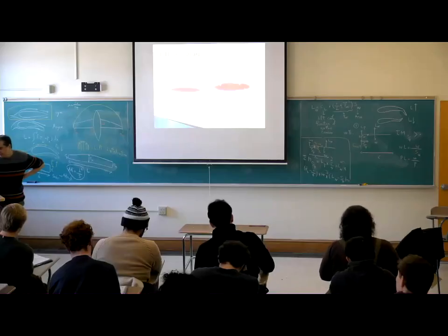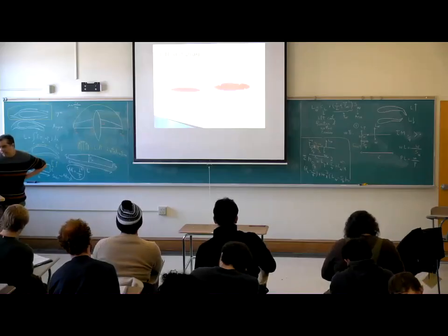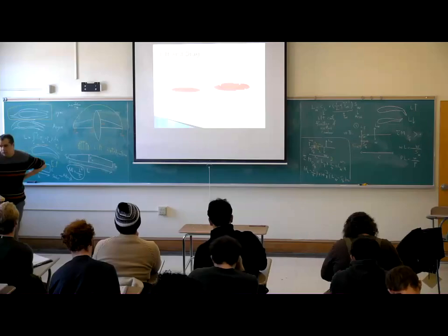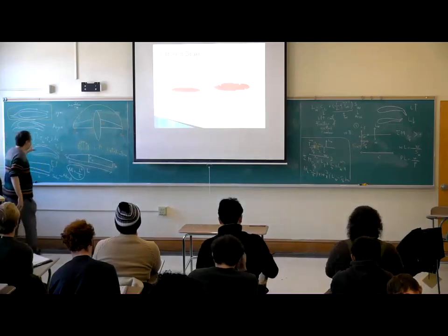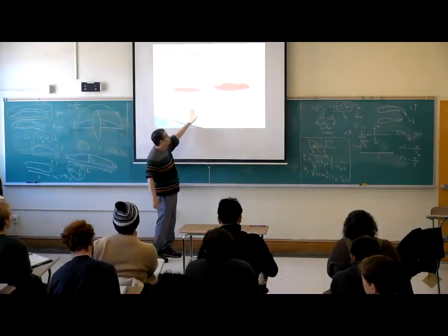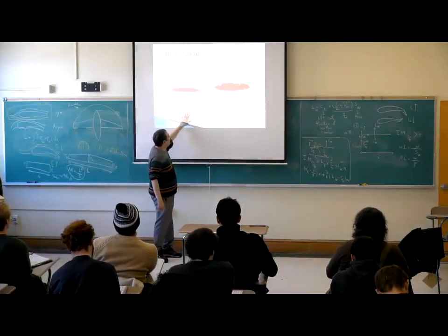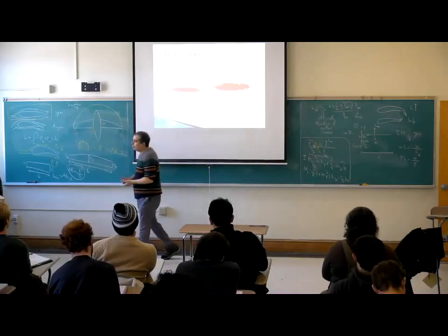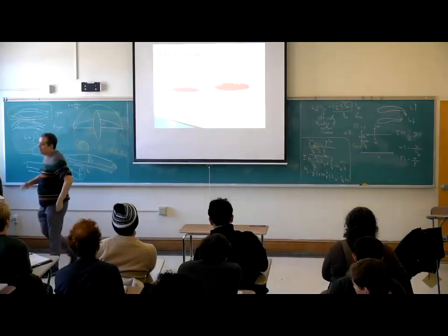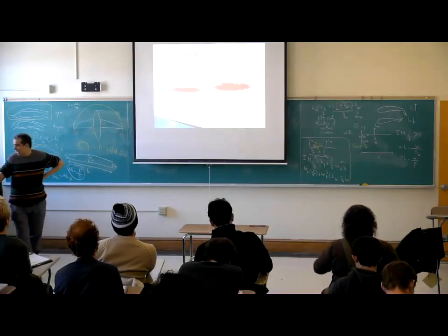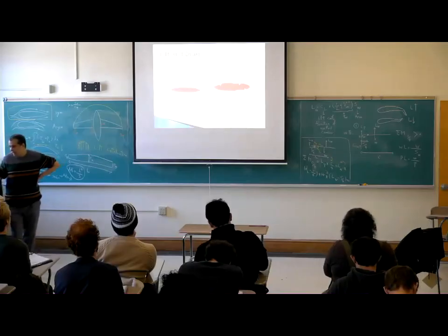Thrust, we skip thrust. Lift and drag. Okay, lift. As I wrote for you here, lift is due to pressure force acting normal to the aircraft, so the imbalance of pressure creates lift. The imbalance of the viscous forces can create drag.